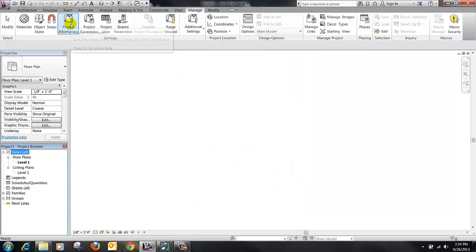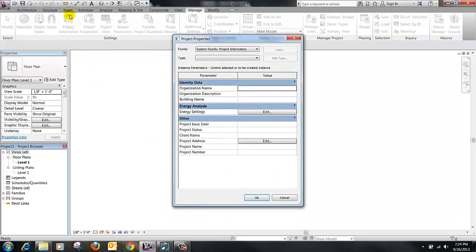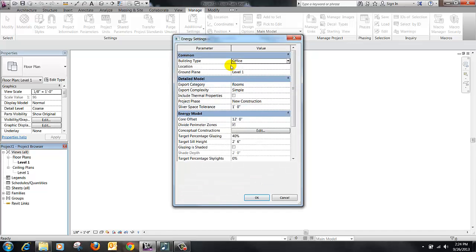Next thing let's look at is project information. Now when we start a project, we want to fill this in, okay, with as much as what you would know. Your organizational name is going to be your school, depending upon which school you're at watching this video. That's what we would put here. Client name, project address, project name, project number, these kinds of things here. The energy settings, if we're going to do an energy analysis on our building, we would make those changes in here. And we'll go through this when we're in a project.